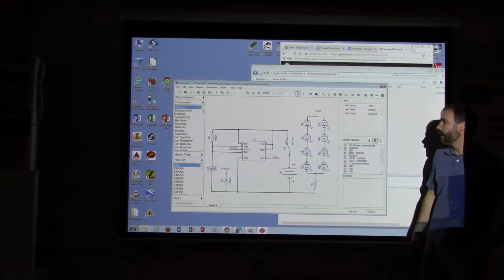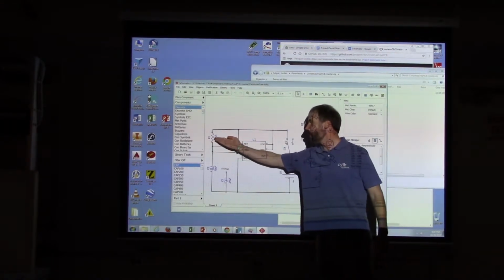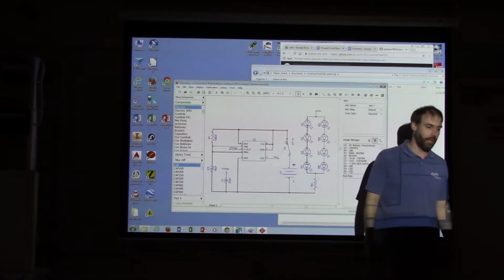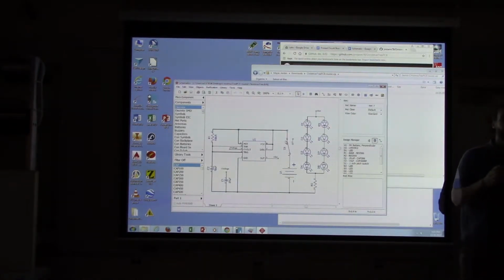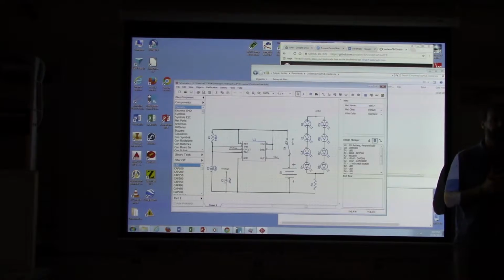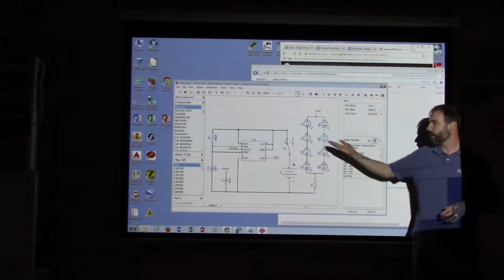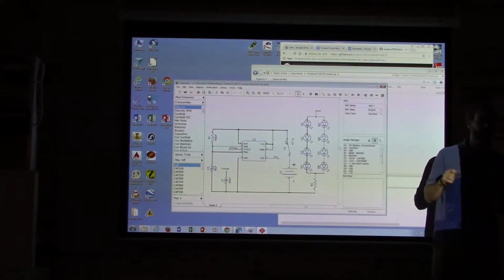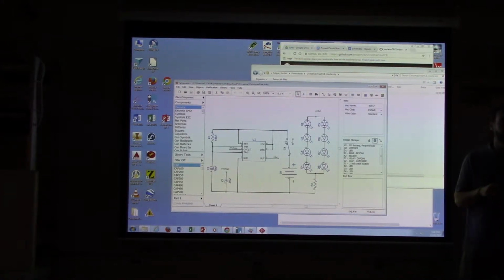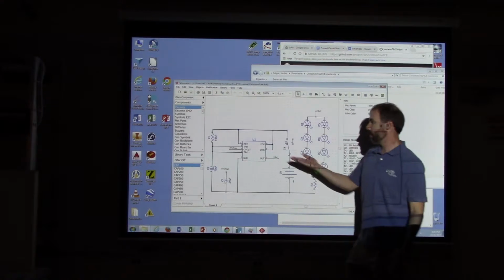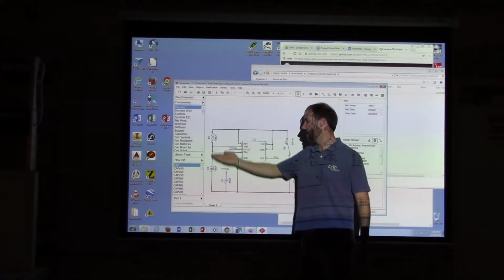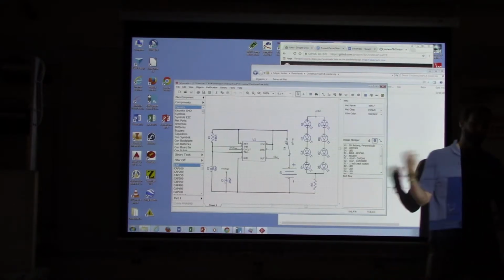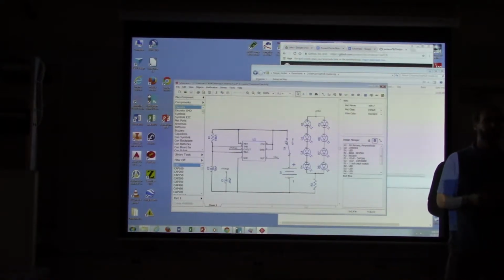And these labels that we put on the components here in our diagram will also show up in our actual final printed circuit board. So these labels are very important because this is how people will know which resistor to put in which place, which capacitor goes where. All right? So they're important when we're making the schematic so that we know that our schematic is going to work right, and then they're important because they transfer over to the printed circuit board as well.